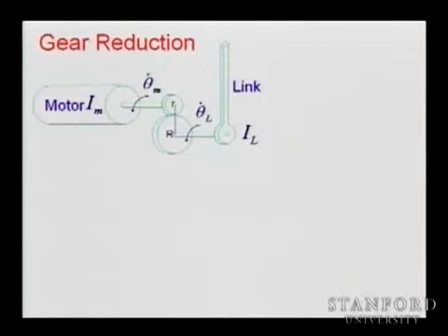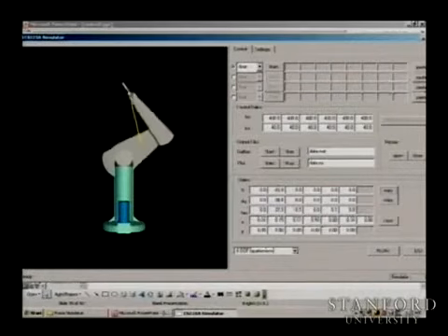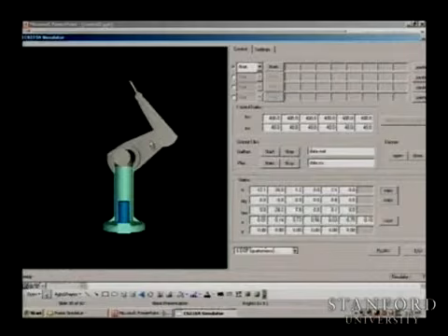So what is the gear ratio here? Come on, we have a lot of mechanical engineers. Is it big or small? So what is a typical gear ratio for a robot? What do you think the gear ratio for joint 2 is? When I move joint 2 here, what is the gear ratio? That's reasonable. Actually, the gear ratios for the Puma vary between like 50 and 150.